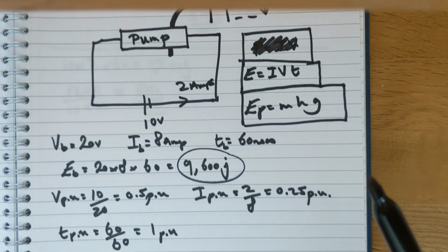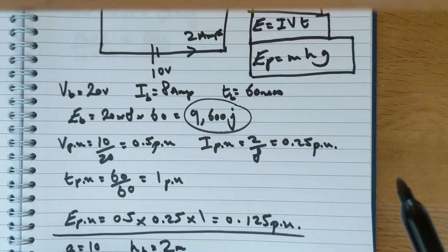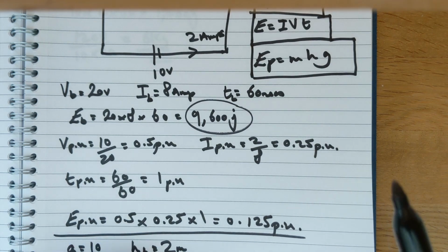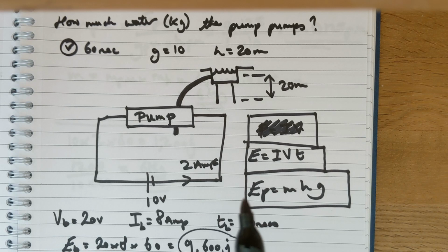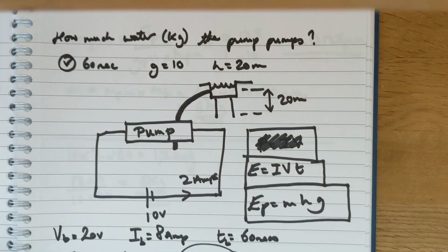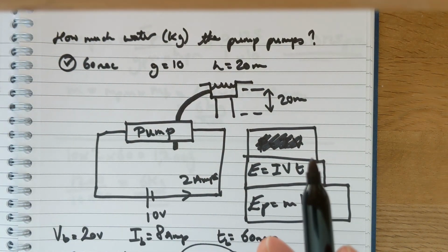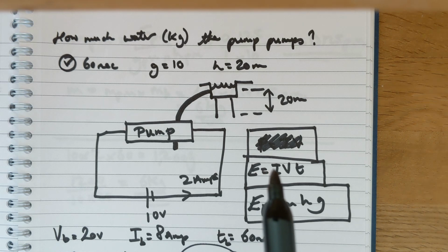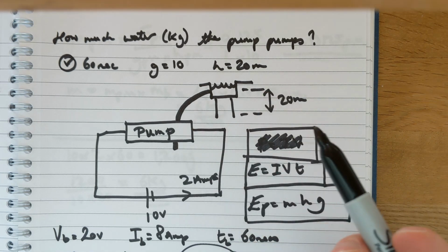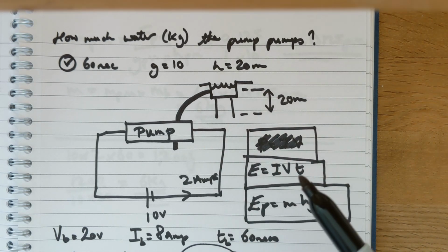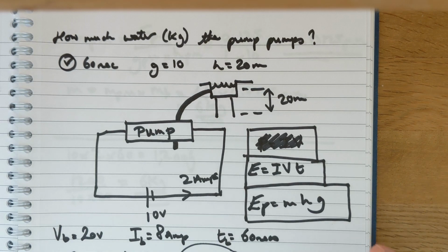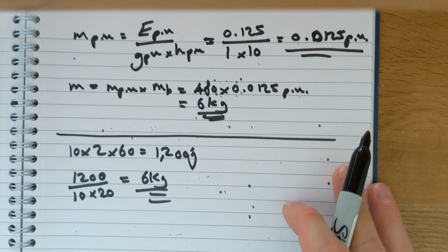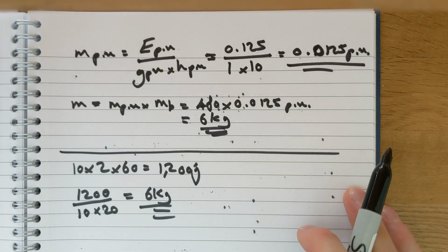And exactly the same calculations can be performed as you would with real values. That is the whole premise of the per unit system. It's stating a value as a fraction of another value, and you can then use these per unit values to do any calculation as long as the base values are all obeying the mathematical rules of the system, and the base values are all carried across.